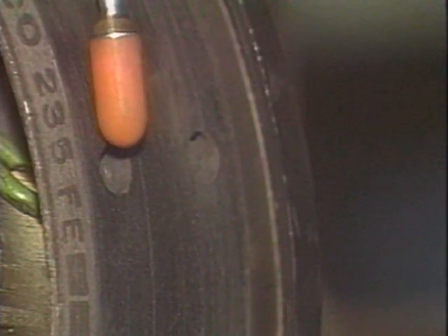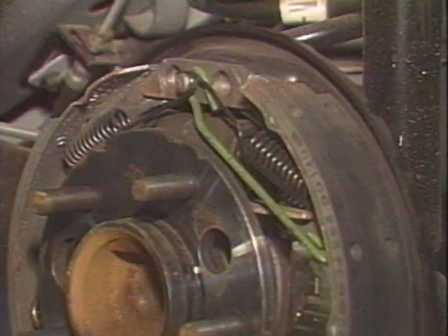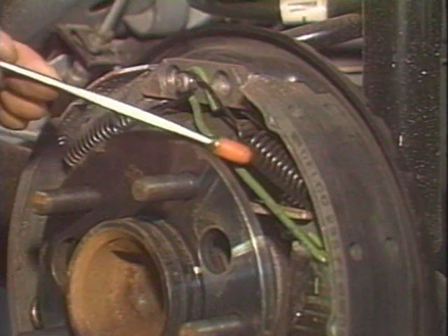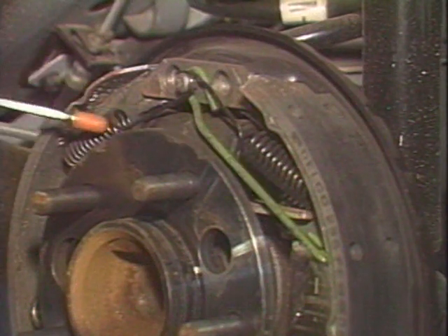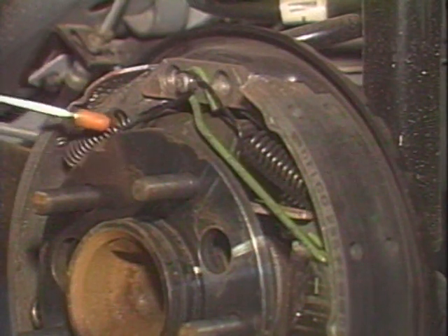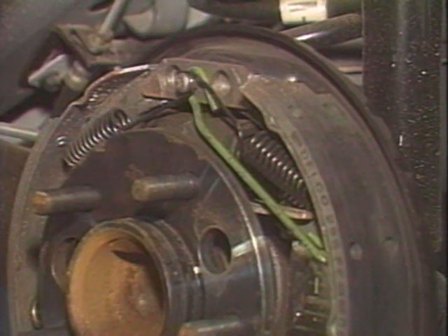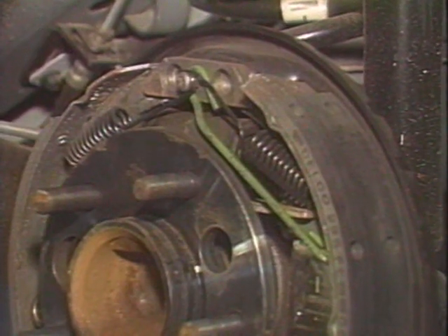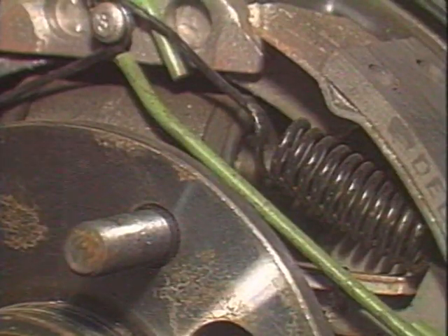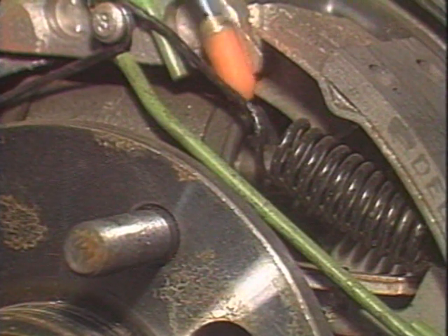The brake shoe linings must not be worn thinner than approximately 1/16 of an inch. The shoes should not be glazed or coated with brake fluid, grease, or differential fluid. Also check the return springs and other parts for signs of overheating damage, often caused by someone leaving the emergency brake on while driving. Check at the wheel cylinder boots for leakage.